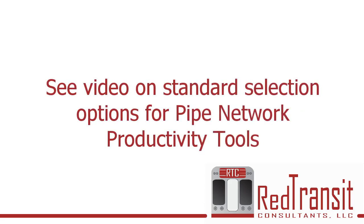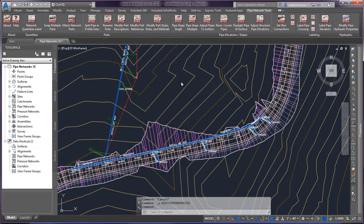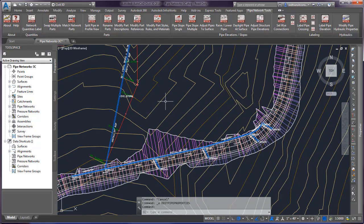This command utilizes the standard selection options of the pipe network productivity tools, so be sure to visit that video to understand how the standard selection options work. This command was built to streamline the process of applying your styles, rules, and materials to pipes, and then also to be able to revert back to the parts list for your default settings for your pipes, which is not a possibility within Civil 3D.